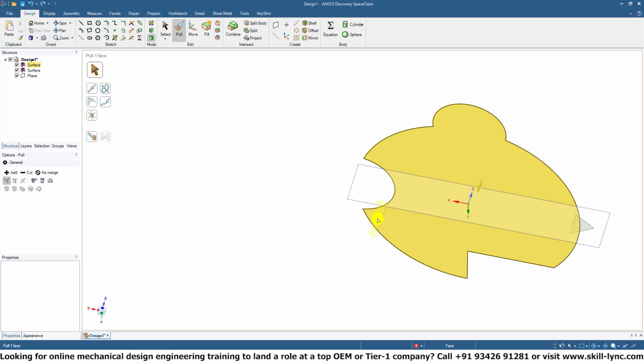And this is important to know, because when you actually import an STL file into SpaceClaim, you won't have any of this helping geometry or past relationships. You'd have to create all of those from scratch if you want to edit the model, and that can get difficult and messy. So long story short, it's good to save a couple of versions of the same file, just in case you need to go back and edit it.